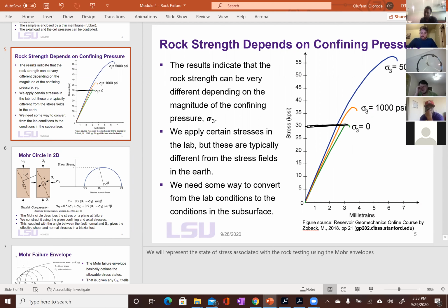So the yield stress, is that necessarily when you don't have confining stress or yield strength? Or is that where it differs from the straight line? Yes. The latter is the correct statement. And in any of this, wherever it differs, so this will be the yield stress at this confining pressure. This will be the yield stress at this confining pressure. This will be the yield stress at 0 confining pressure.